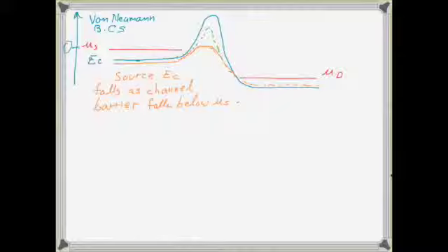And this happens when I'm not using any of those generalized boundary conditions, so the entire region is non-equilibrium right out to the ends. I'm calculating the charge using the non-equilibrium expression throughout the entire region. There are none of these equilibrium regions here. I'm using the non-equilibrium charge expressions everywhere.